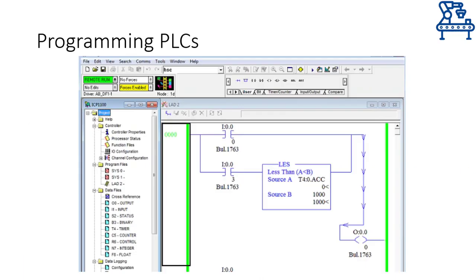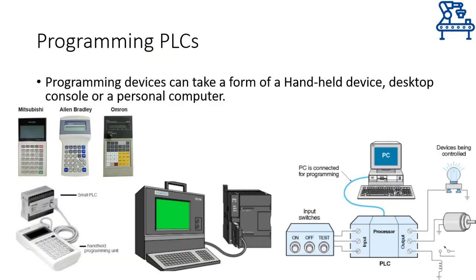As the last thing related to the introduction of PLCs that I want to talk about is, I guess, the most important one, and that is how to program a PLC and what are various things we should be careful about. Well, for starters, PLCs don't come with a programming device. We normally need a personal computer or sometimes a handheld programmer to program the PLC. Once we have a programming device, the next thing we need is the software IDE that can help us in creating programs and communicating the program to the processor of the PLC.